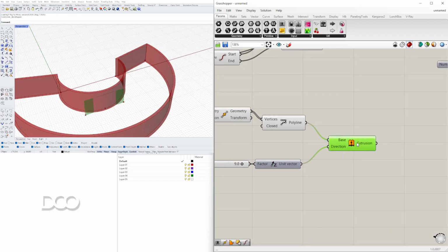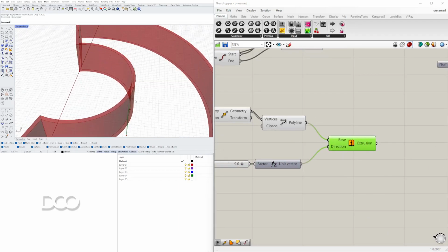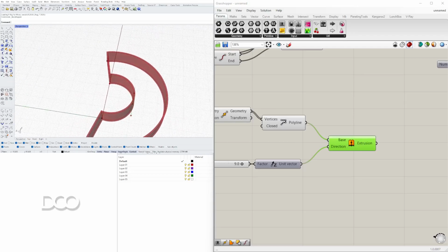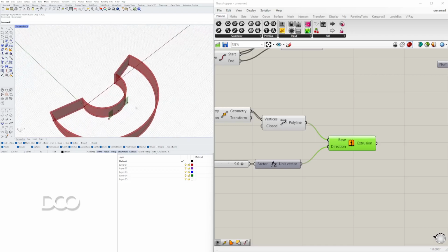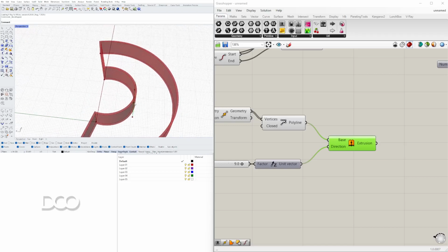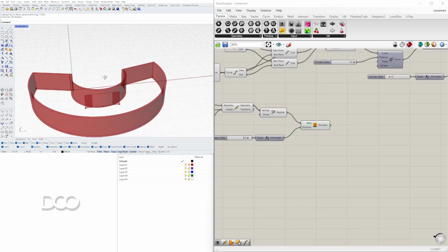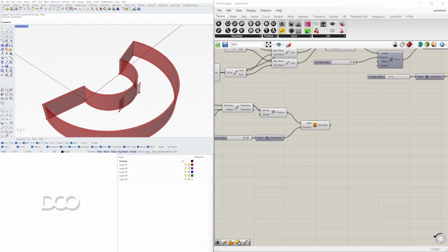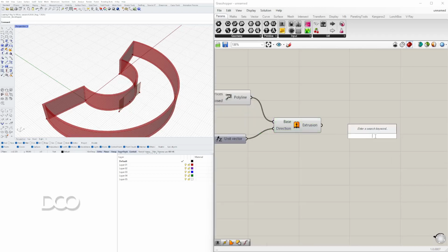Now with the surface, we can take this and extrude it in either Y or, yeah, we have to do it in the Y direction. So one trick is going to be to move this in this direction and in this direction, or move this surface in this direction and then extrude it in the opposite. So let me show you that trick. And that's to make sure that it intersects the form completely. So we'll take this and we'll first move it in the positive Y direction.